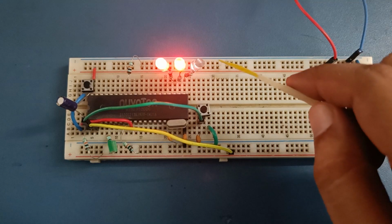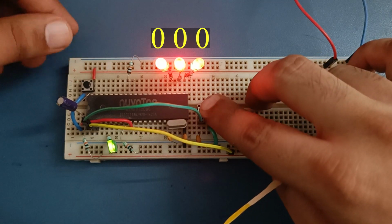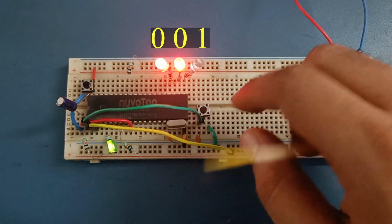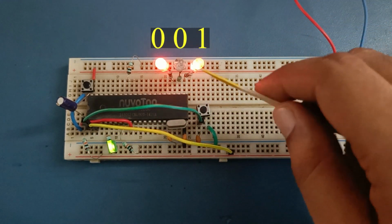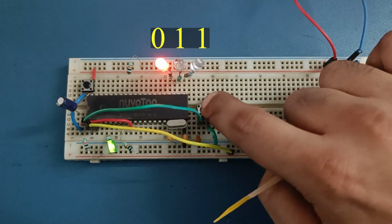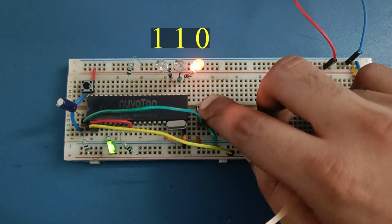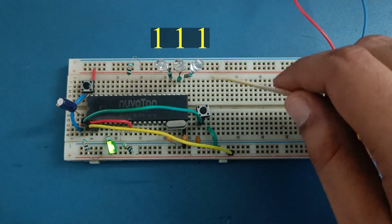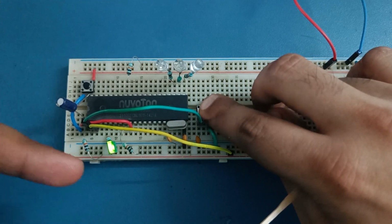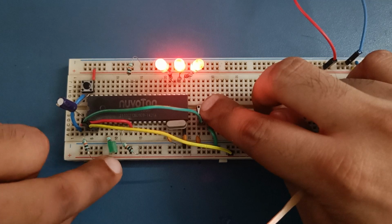The LEDs are connected in common anode. So all these were 0, 0, 0. If I give one count, it will increment and become 0, 0, 1. So this is 1. Then 0, 1, 0, which is 2. This is 3, 4, 5, 6, and 7. 7 means all 1. This is FFFF. So after FFFF, if I give one count, it will overflow. So this EXF2 flag, which is represented by this LED, will toggle. So this will go low.